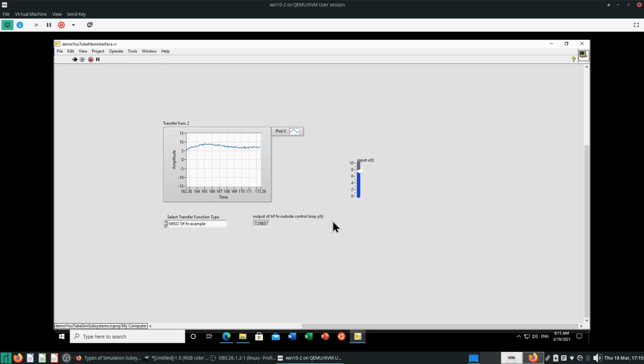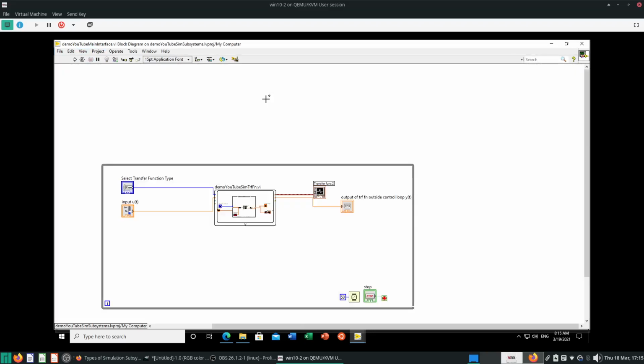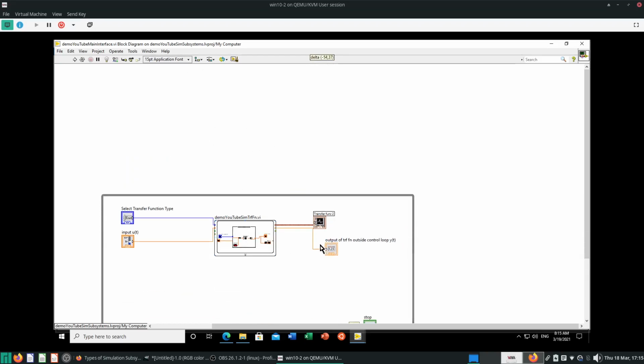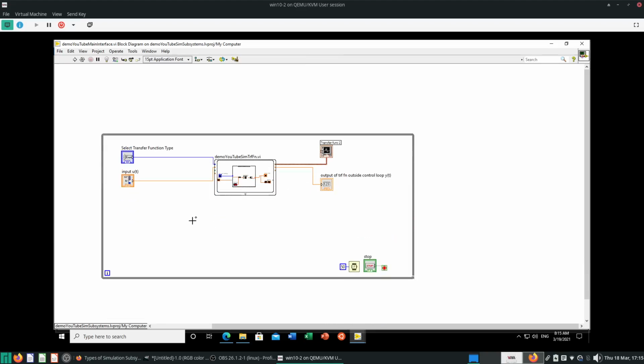Alright, so now you have a transfer function equals to 1, then we can just shift it up and down. I think that's all I want to share. We'll deal with this time issue later on, but you can see the latency, the lag is very low, and more importantly, we have effectively cleaned up the whole block diagram. So now this looks very simple, very neat, and that's important if you have a lot of components here.